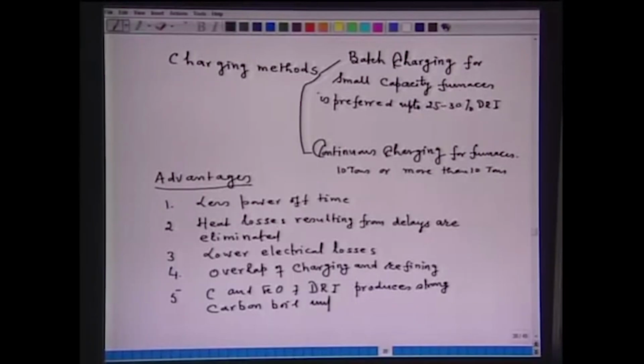So, this carbon boil improves heat transfer and slag metal mixing. These are the certain advantages associated with continuous charging, and now it is obvious also, anything which is continuous, all the delays which are associated with the batch are eliminated, and hence the advantages are obvious.